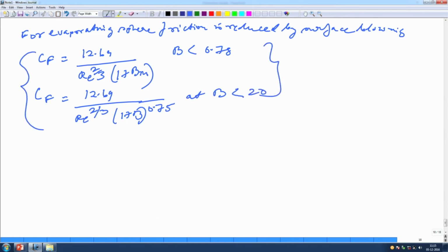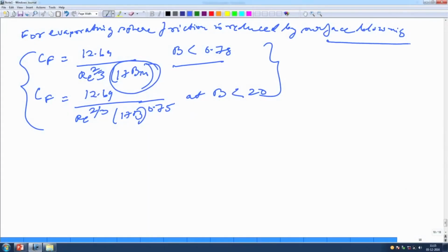Got it? You got it? So, this particular part is quite obvious. Now, the skin friction coefficient is actually reduced because of the surface blowing, because of the thickening of the boundary layer, right. This will in turn reduce your US, that means the surface velocity that you are going to generate inside the liquid phase. Now that we have analyzed everything, you know US and everything, the transient heat transfer can now be solved.